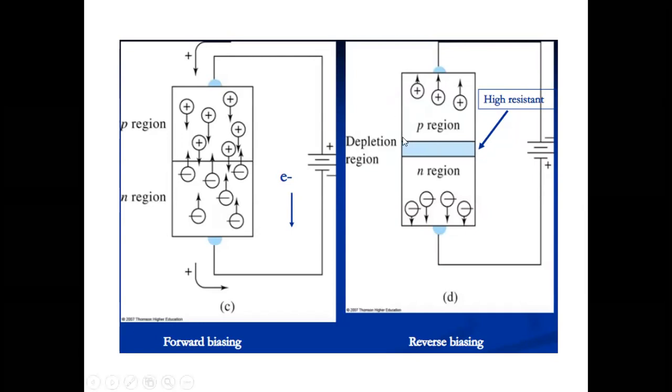That's how the depletion layer or depletion region is formed. Now there are no electrons or holes in between this range, right? That is how the depletion region is created. When we give the reverse bias, the depletion region will be created like this.